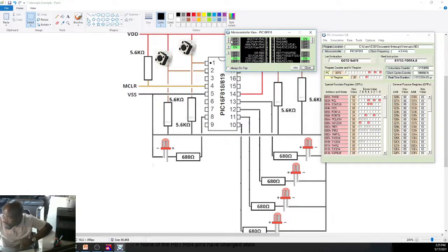Right. So if I make them all ones, you see, my exclusive OR, it is still working there regardless, because exclusive OR is making use of those 2 inputs. If I make all of them ones, I need to generate an interrupt for that output on port B to be updated. Generate an interrupt. You will read all of those. They are all on, all port B4 to B7 are on, right? So basically, that's what interrupts are, and that's how we make use of interrupts in the PIC microcontroller, right?